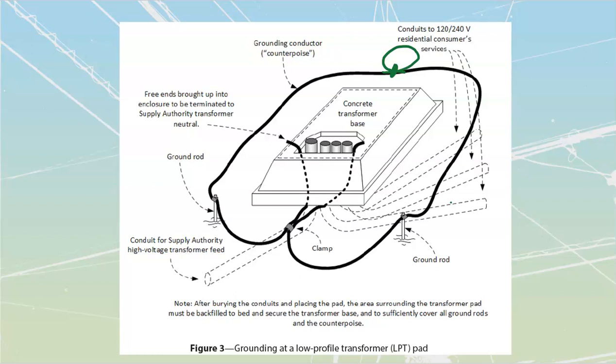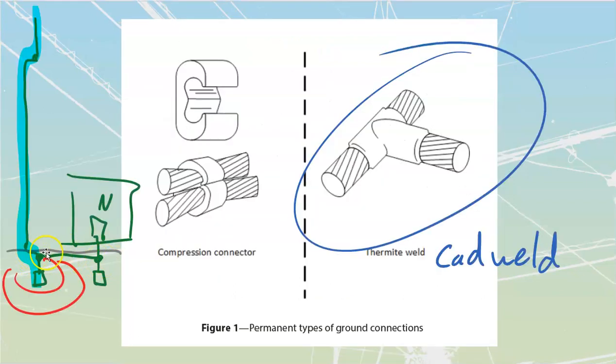We do have to make sure that our conductors and electrodes for the electrical system grounding, we're not using them for our lightning rod system. That would then attract it down there. We have to maintain that 2 meter separation we talked about. And then the lightning rod system grounding electrode has to be bonded to our system one. We talked about that as well. And that bonding has to happen underground. All of that over there.